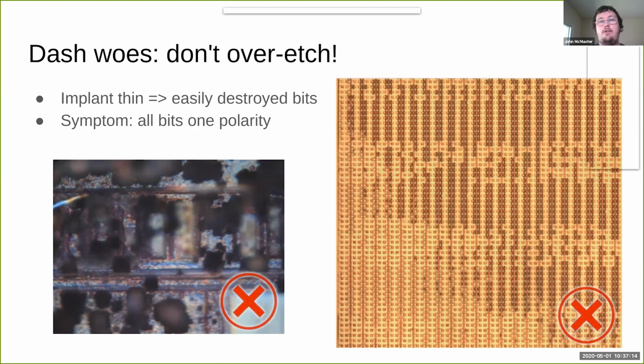And in order to do these very short times, you also need to be very careful. Instead of taking a chip out, which may still have droplets of etchant on it, you need to add a lot of water to that solution to even out the change between etching and not etching.